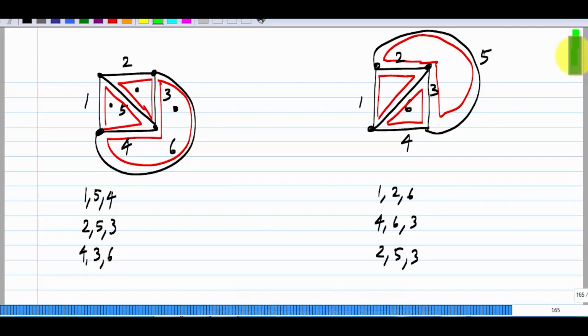So using mesh currents as variables: with nodal analysis we chose node voltages as variables and solved for them. In mesh analysis we will use mesh currents as variables and solve for those variables. From that we will be able to get all the other currents in the branches, and from that voltages in all branches using element relationships.